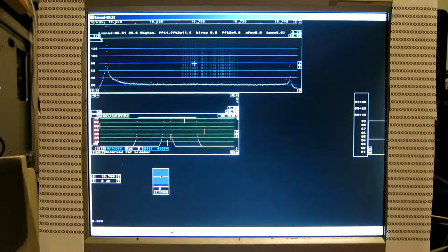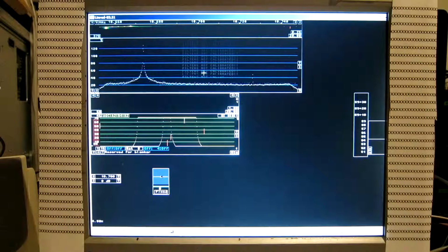And look at the result. The signal is at about 130. The mirror is at about, what can it be? 75. So that is 65 dB. That is the ends of the spectrum where balancing is worst. So I go further into, and you can see when we are 10 kilohertz from the end, we have 130 and 50. That is 80 dB. That is more or less good enough.